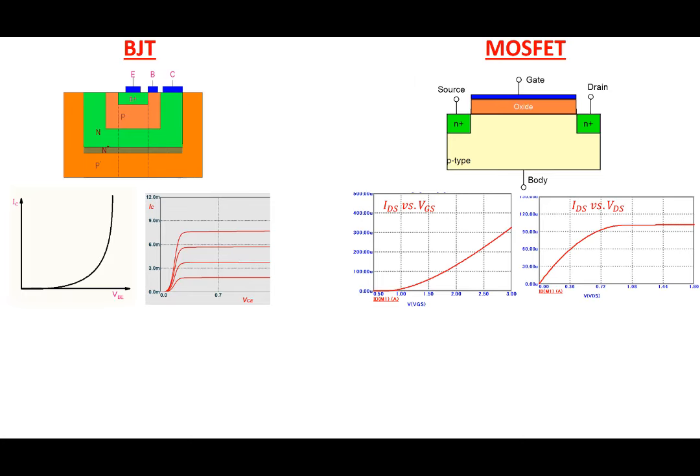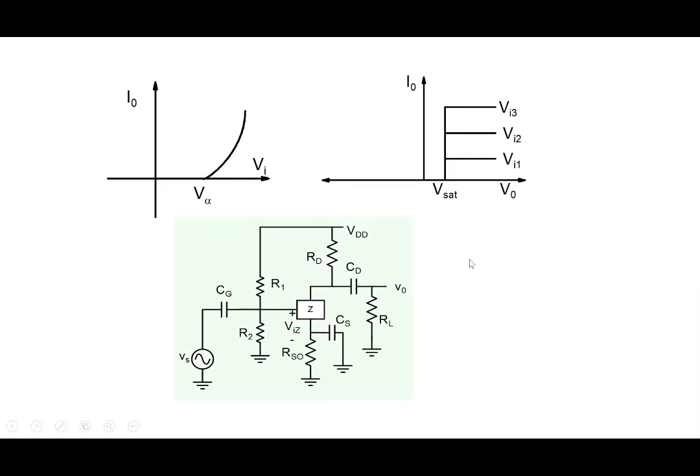All right, and we saw earlier that these are not ideal transistor characteristics, but if we bias a transistor here and somewhere here, similarly we bias a transistor here or somewhere here, then by the methodology that we had discussed earlier, we can build amplifiers. All that we need to do is, we took that hypothetical element called Z in the last lecture. We can take this out and substitute it by a transistor, bipolar or a MOSFET, and our amplifier would work and amplify the signal that is shown over here.